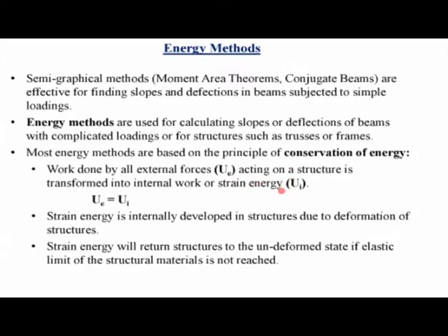Now, how does the strain energy develop in the structure when you apply loads? Basically, when you apply loads on a structure, all the components of the structure undergo deformation internally, and the strain energy is internally developed in the structure due to the deformation of its components. Because of this strain energy, the structure has the ability to come back to its original shape once the external loads are removed.